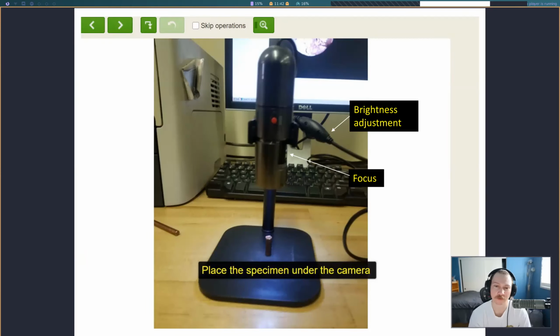So we're going to calculate both the shear stress and the bearing stress in this experiment. Just like with lab 5, we're going to use this camera to take a picture of the fracture surface that we have. So this is that small little piece in the very center. We're going to take that and look at that shear surface that we have.